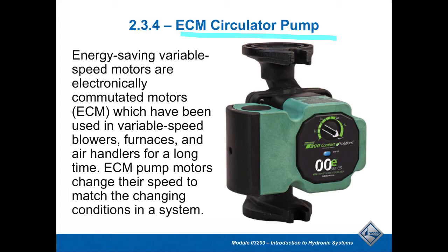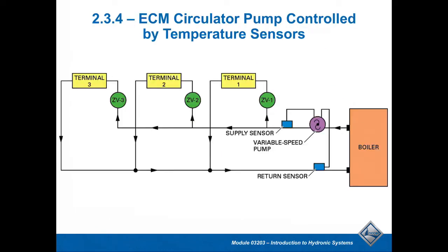But ECM pumps, they do a great job, and they also give you the ability, the manufacturers can program certain parameters in there where you can say, I want it to maintain constant speed, or I want to maintain a constant pressure, or I want it to do the best that it can to try to maintain flow. So it gives you a lot of variability. They're really awesome.